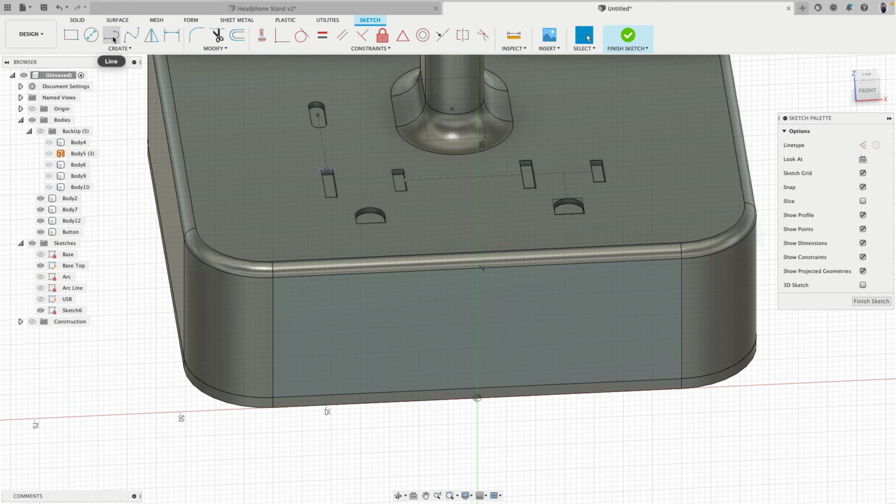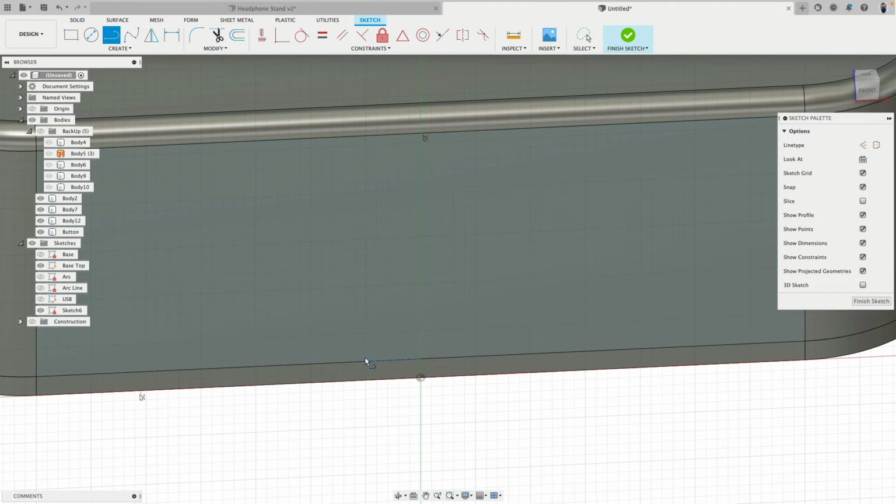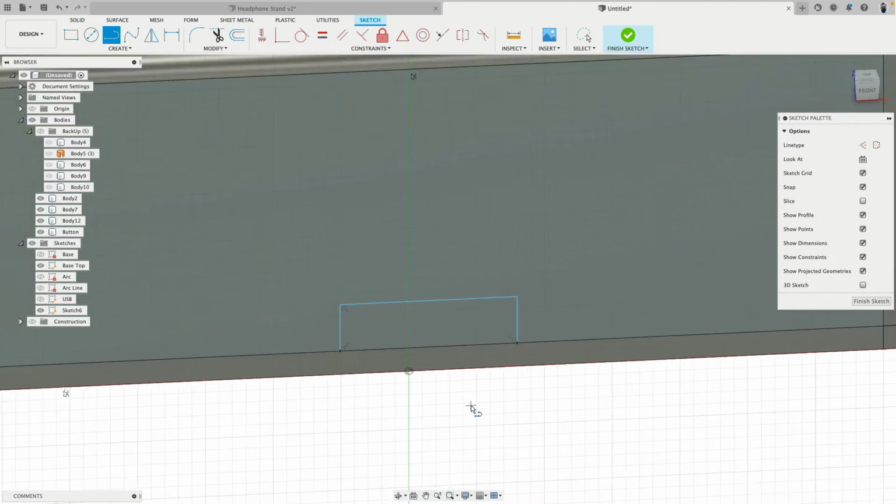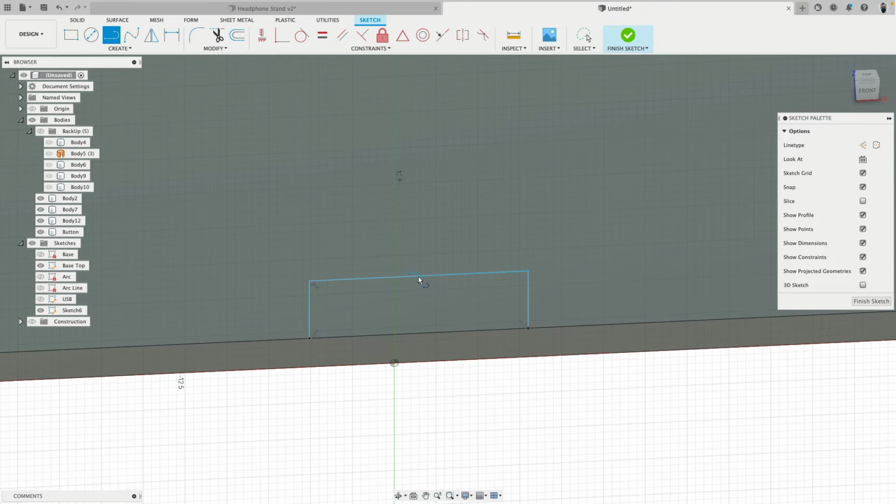There we are. Now a new sketch on that thing. Here's a line. I make a longer line, and there. And then from the midpoint, I make a line down to the other midpoint. And this one I will vertically constrain. And this line is a construction line. Press X. Cool. This line will be 5 millimeters, and this will be 15.